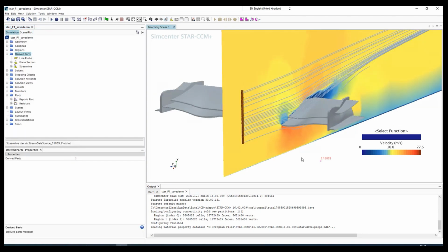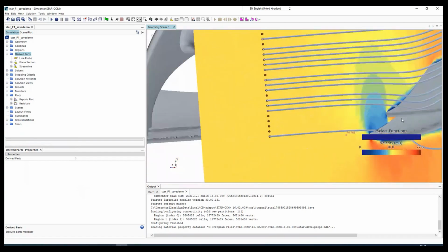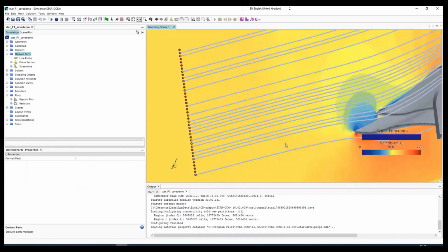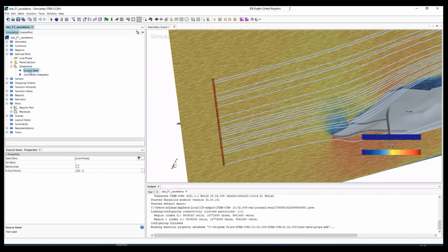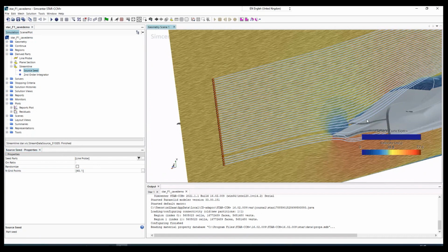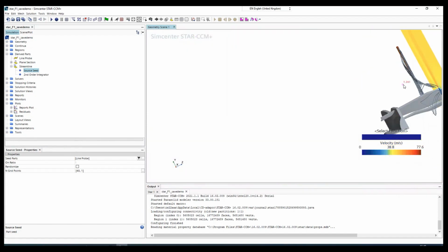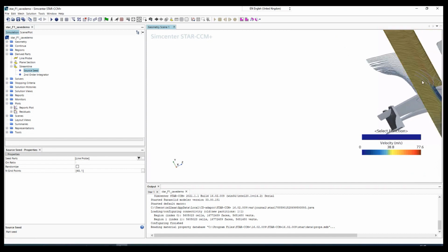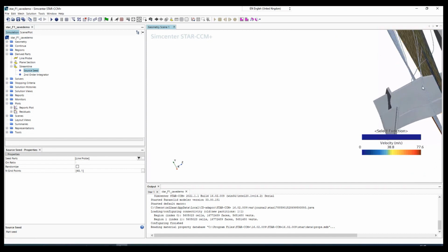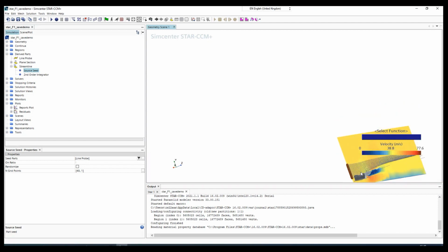Okay, so for now, you can see the streamlines. Okay, so this is a streamline. And potentially we can add more streamlines. So what we can do is I just use 20. So if I do 40, it will produce more streamlines. And you can see there's also flow diverted. Yeah, it's not within that plane, but it's diverted to the other. The seeds is going into other planes, and that's the vorticity. So in the next step, we will visualize the vorticity.